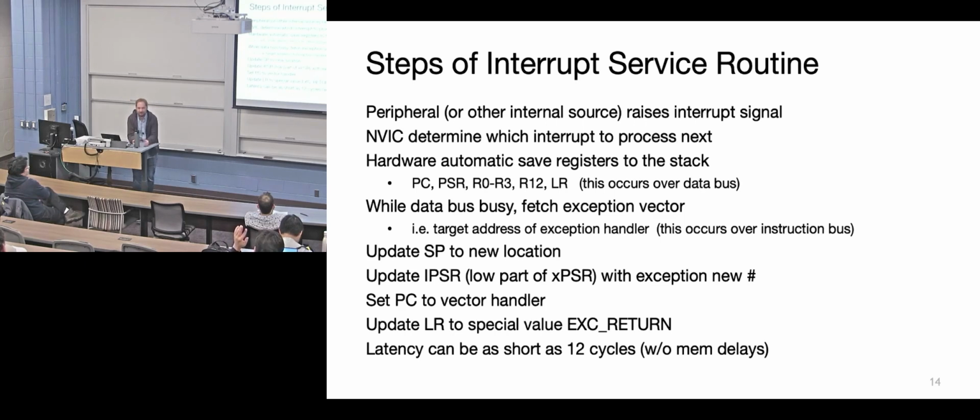When we're doing stacking, the reason why we don't say R12 to R11 is because we assume that it's ABI compliant. Stacking for an interrupt, just like another function that a programmer would write, should be ABI compliant. It would be a waste of time if we had to take the entire 16 registers and save them. You could do that, but then you'd take longer to enter your interrupt. So the trade-off is we're only going to give you 4 registers of scratch space, and we get into the interrupt faster.